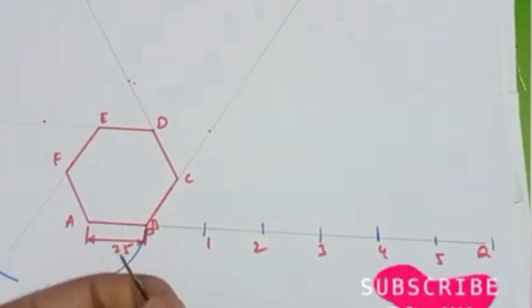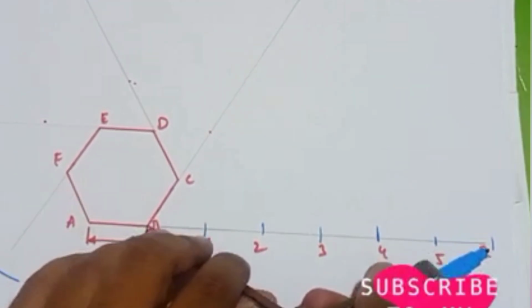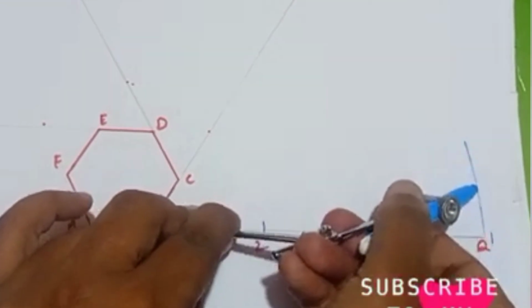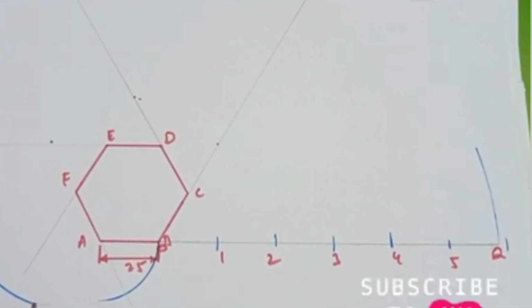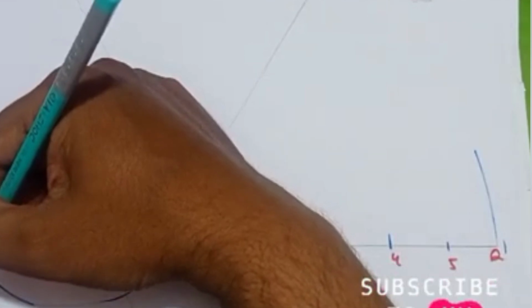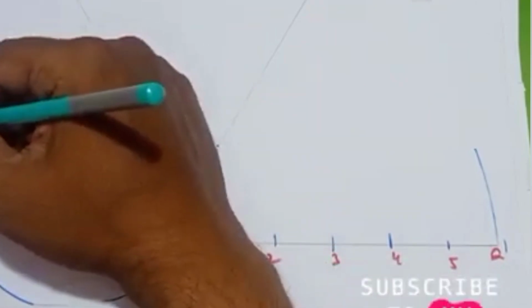Now we have to connect all these cut arcs with a smooth curve. Here from P to Q, I'll be drawing one arc so that it will be convenient for us to extend it and make an involute. Initially I'll be connecting with the pencil so that drawing the final one will become easier. So try to draw the smooth curve here.